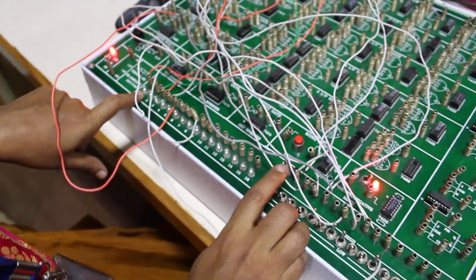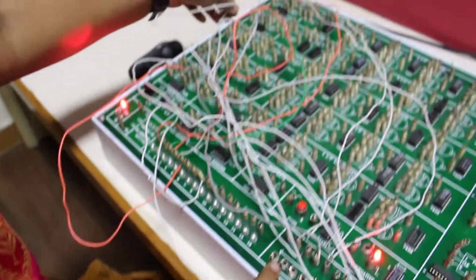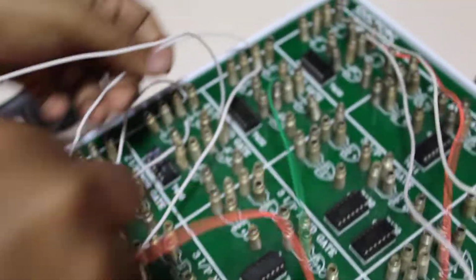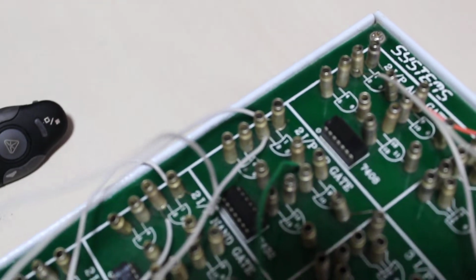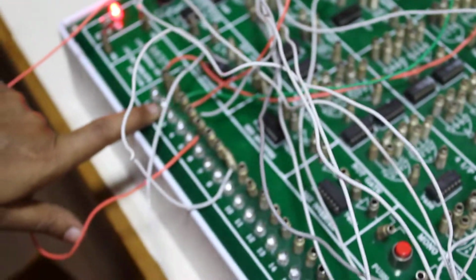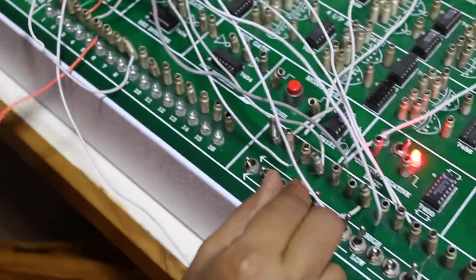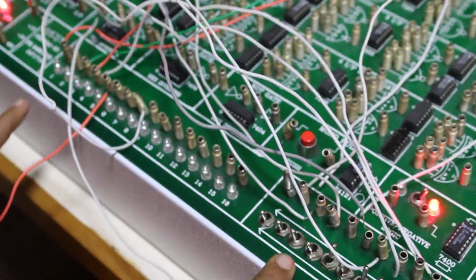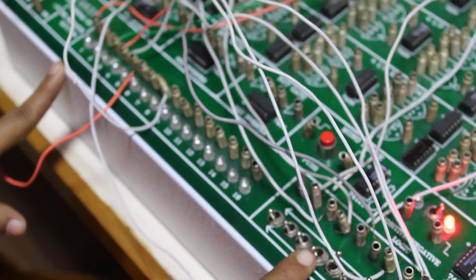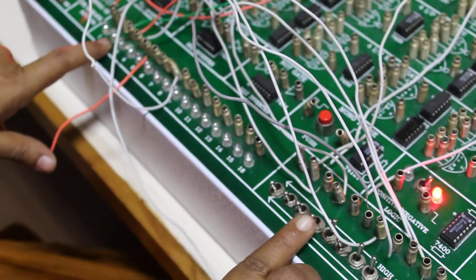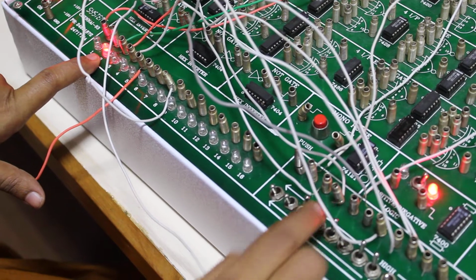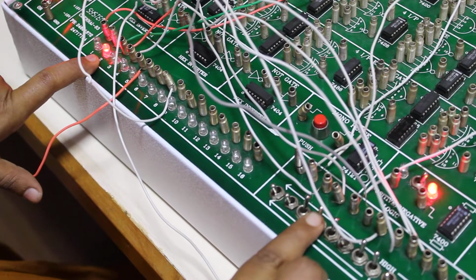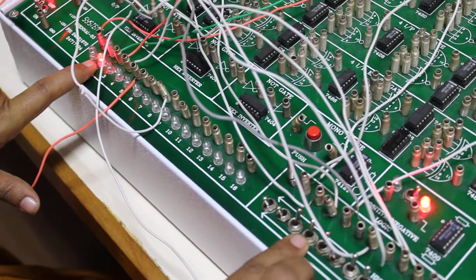Okay. Now we'll move on to the second gate, that is the OR gate. The 2 inputs are connected from the OR gate, and given as the input here, and the output is shown by the green wire, which is the second LED. Now what is the function of the OR gate? If either of the inputs is 1, your output will be 1. So the first condition is 0 0, so the light doesn't glow. When it is 0 1, the light should glow. When it is 1 0, the light should glow. When it is 1 1, the light should glow. This completes the OR gate.